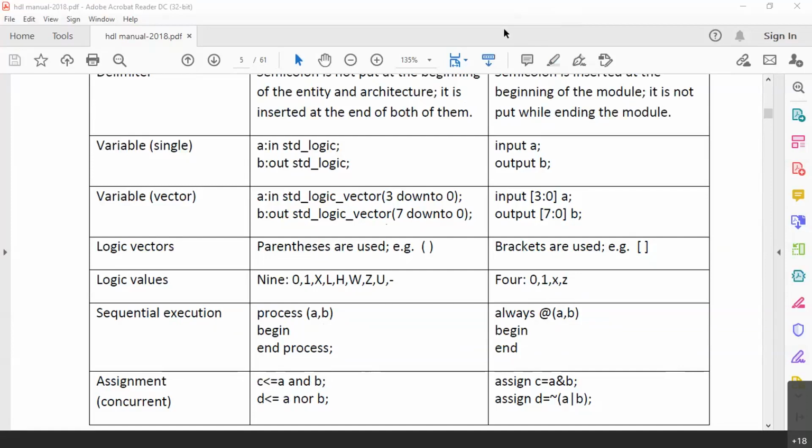That is why you should not call this particular symbol a less than or equal to symbol. We should keep on calling it an assignment operator. It is a less than or equal to symbol only when we use it in mathematics. But in a software language, when we use it, this is an assignment operator. Similarly, in Verilog, you have to specifically say the word assign and use this symbol, equals. Now in Verilog, this equal symbol is the assignment operator.